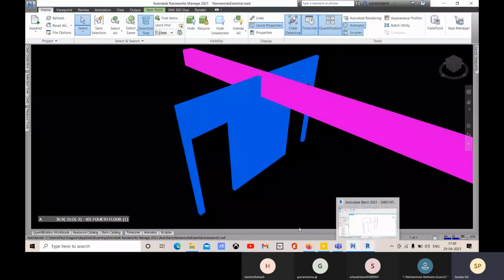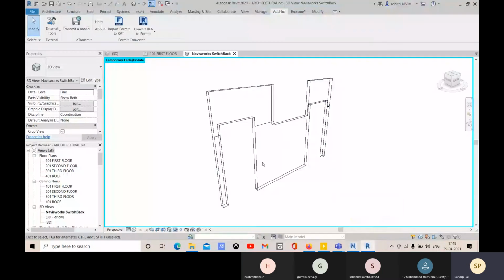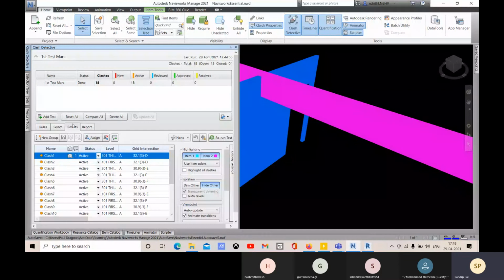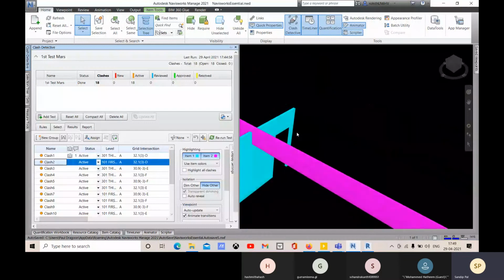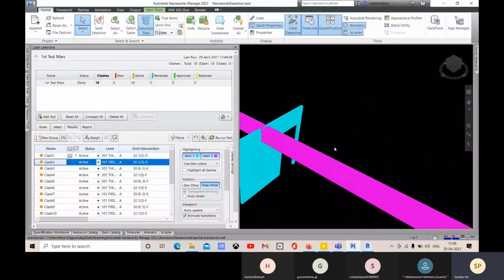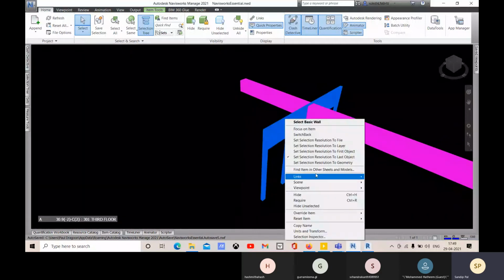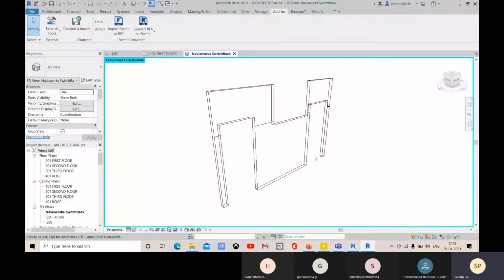So here you have to upload it again. So you just have to find out all these clashes. Right now you don't need to upload it here. Right now, come to all these clashes, just hide others and select it and go for this switchback, and it will open up in the Revit, and you will solve all these clashes as per your direction.